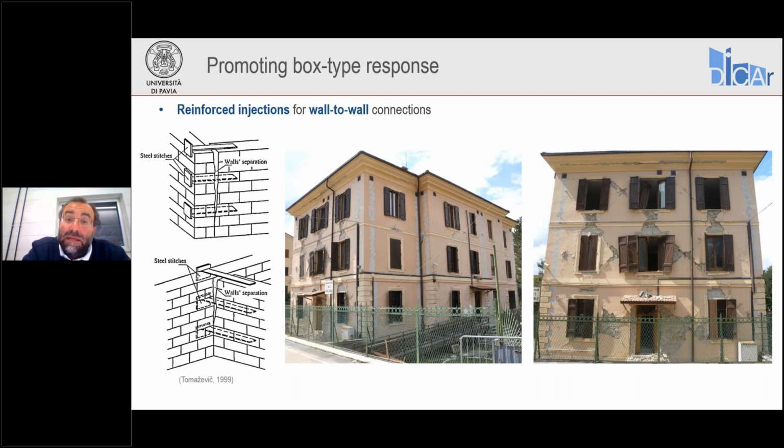You see, they were very, very effective at tying the building together in combination with tie rods at the top. The fact that the building was heavily damaged in its plane meant that this building had to be torn down after the earthquake. However, no one died in there, it didn't collapse, and it survived the earthquake, even though heavily damaged. All the damage is in plane.